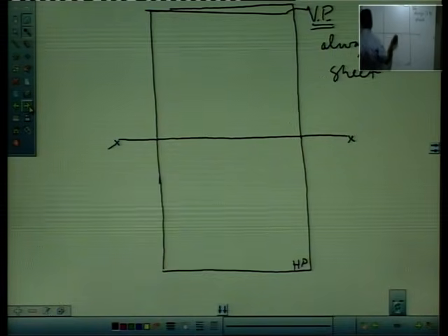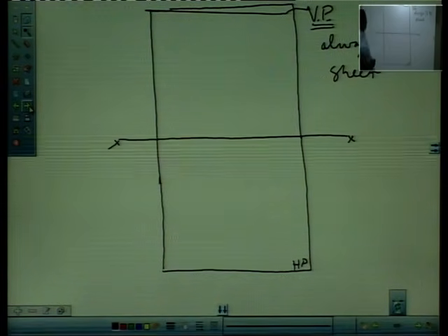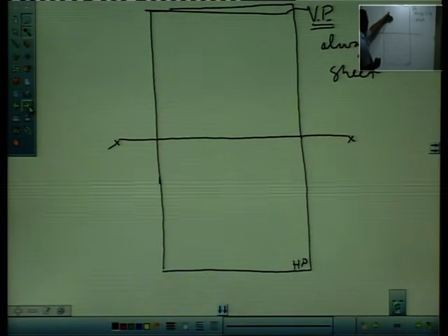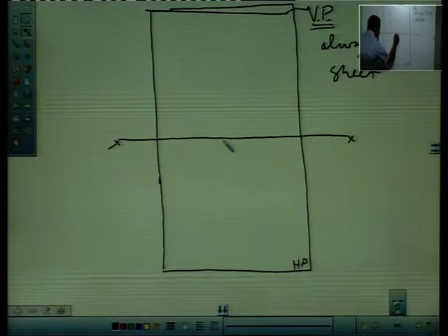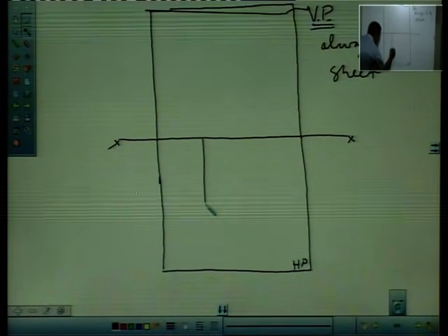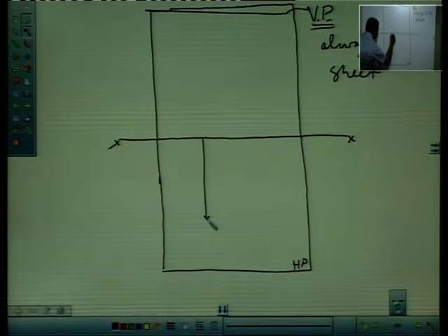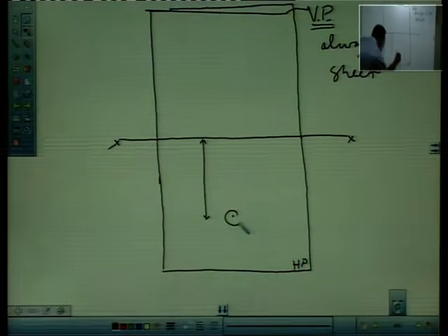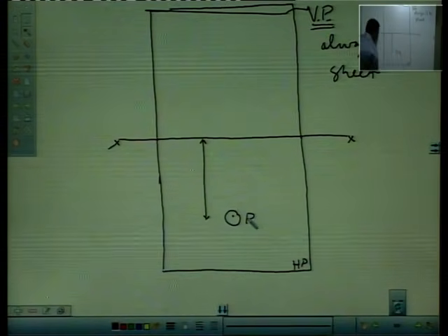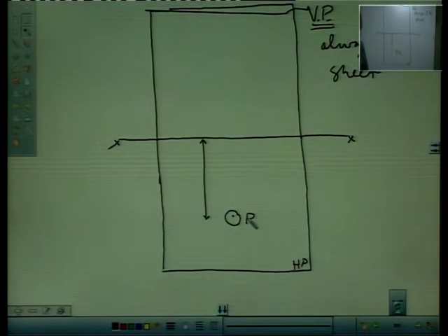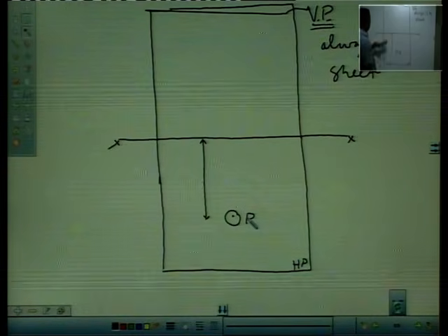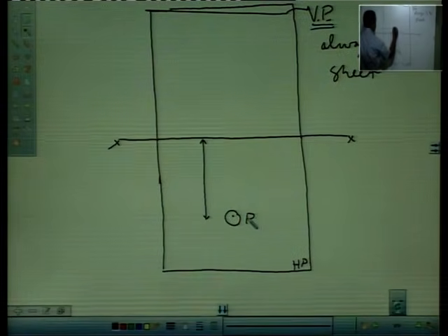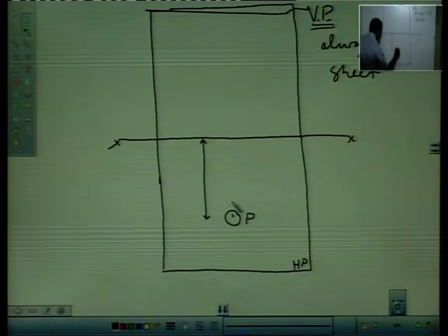So, as per the statement, our point is 10 centimeter in front of vertical plane. So, this is vertical plane. We will draw a line 10 centimeter like this and draw our point here. Say this is point P. And it is 5 centimeter above horizontal plane. The height will be shown in the vertical plane. Draw a guideline from here.